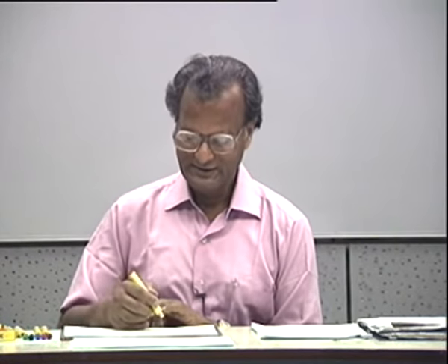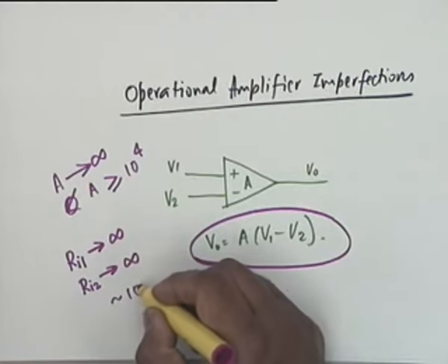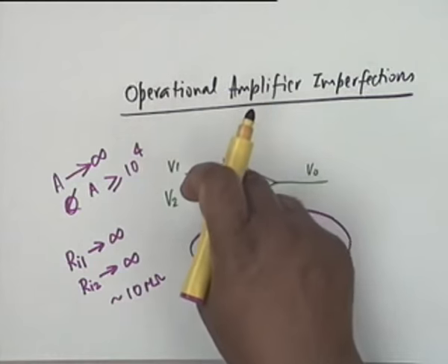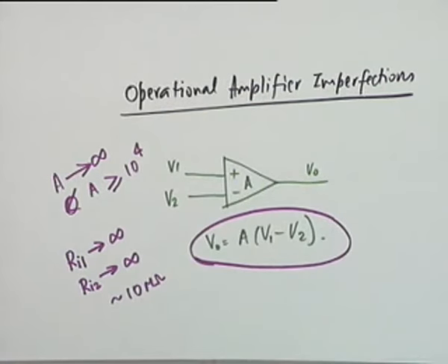And a differential amplifier, at the base, the impedance is not infinity. It always takes a base current. Okay? And the usual practical figures are of the order of 10 meg. The differential input impedance, that is between V1 and V2, is also of the same order, 10 meg. That makes a good op-amp.